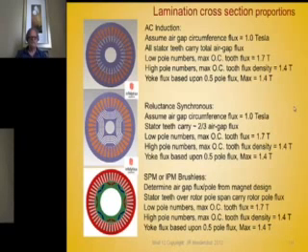Let's start with the induction machine. As I have indicated in other lectures, we want to assume some sort of air gap circumference flux density as high as 1 Tesla. I doubt we can get it that high, but let's shoot for 0.8, 0.9, 1 Tesla. All the stator teeth, because they're connected to the air gap, have to carry that total flux. So if you have 4 poles, each pole is represented by many teeth, and all those teeth have to carry the flux.